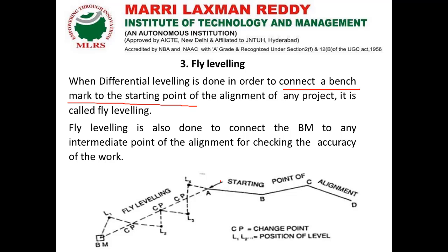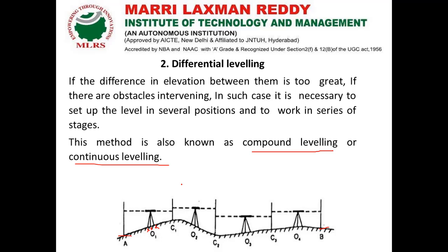Here we need not take any intermediate sight reading, only backsight and foresight readings, in both differential leveling as well as fly leveling.